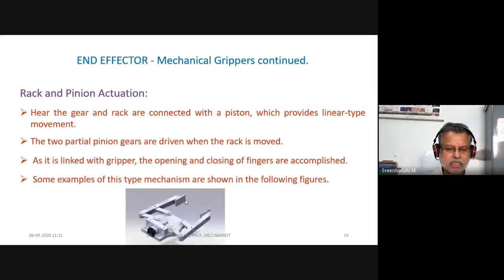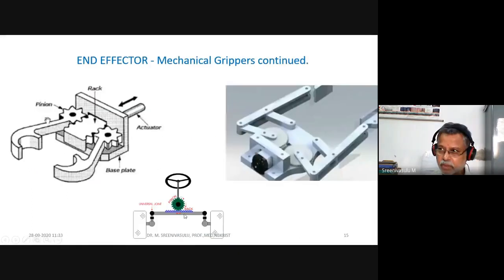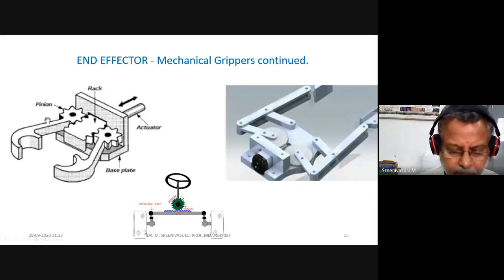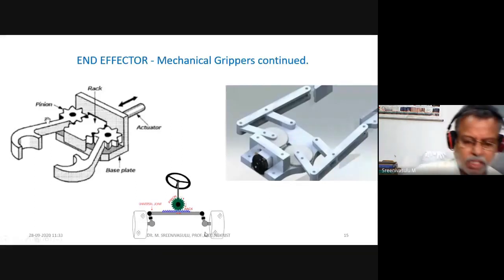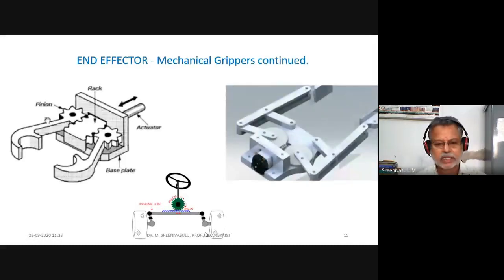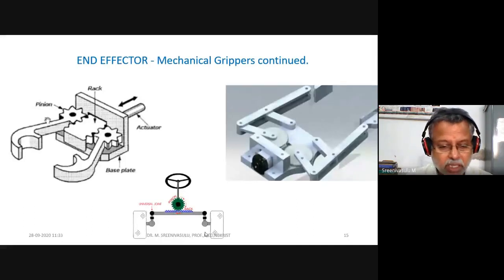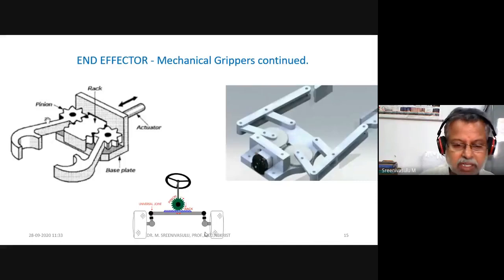Let us see this. See here, you have got gear wheels. When the rod is moved backward and forward, you have a toothed rod, and this toothed rod maintains contact with these rotary gear wheels. And here, this is the best example you can visualize when you are steering your car with the support of a rack and pinion arrangement. The front wheels move, either taking a left turn or a right turn.